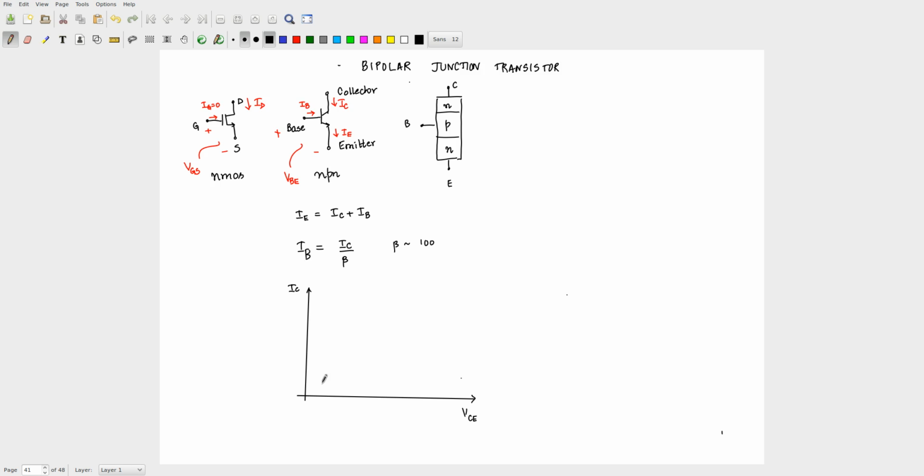The speaker who came last semester, for example, and spoke about inductors, if you remember those who attended, mentioned that the last stage power amplifier design is very key today, and that in fact it limits the choice of companies whom a phone manufacturer can approach. There are a large number of companies that give you the technology for fabricating all of these MOS transistors, and also the circuit libraries that you can use to simulate. But many of them don't have very good power amplifiers, and hence in the long run people don't prefer using those technologies. So the bipolar transistors are important, and when you do a discrete kind of design, you will see that bipolar transistors are still very popular, also for power amplifiers and things like that.